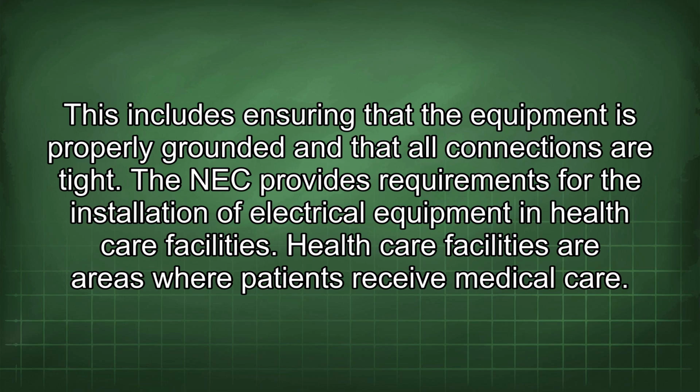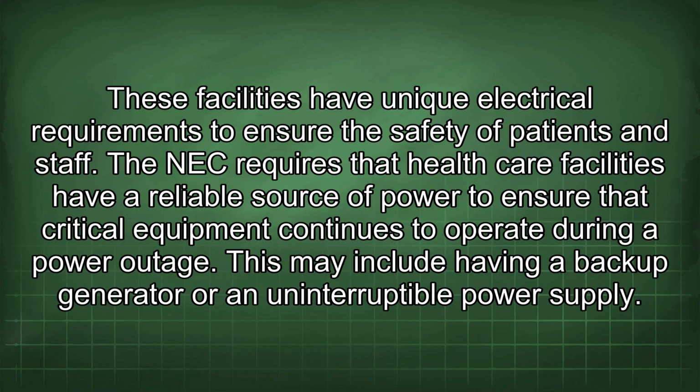The NEC provides requirements for the installation of electrical equipment in healthcare facilities. Healthcare facilities are areas where patients receive medical care. These facilities have unique electrical requirements to ensure the safety of patients and staff. The NEC requires that healthcare facilities have a reliable source of power to ensure that critical equipment continues to operate during a power outage. This may include having a backup generator or an uninterruptible power supply.